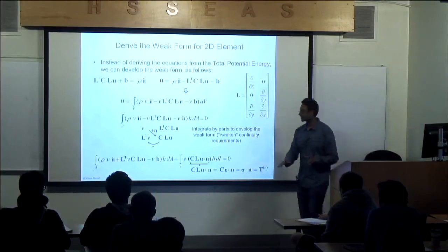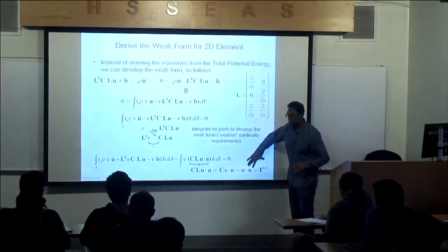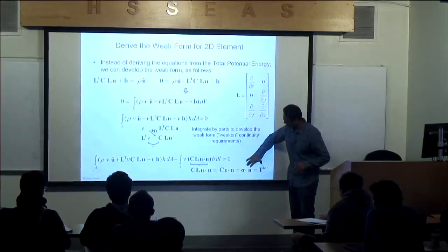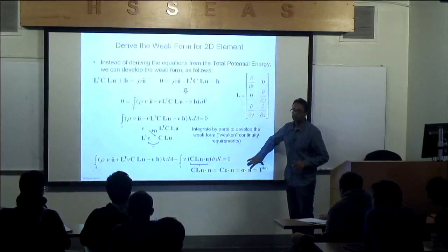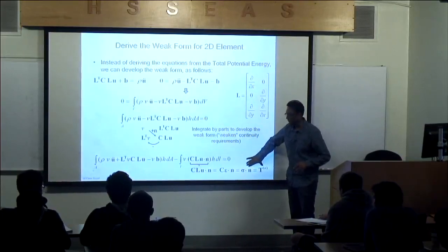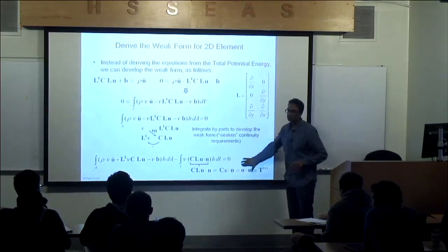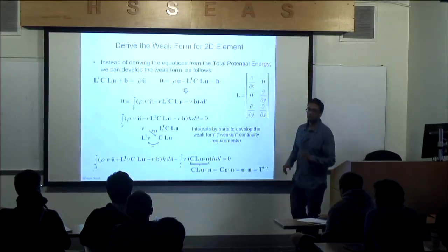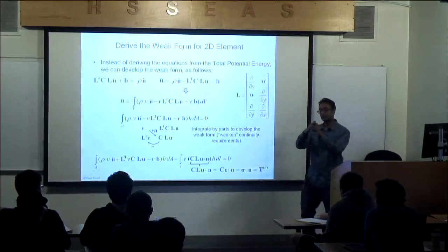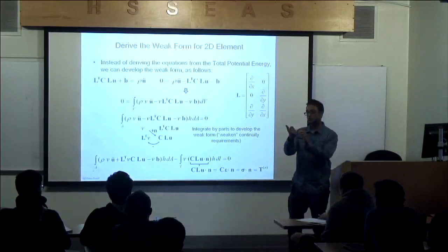If you take a more advanced course, I can show you by first principle that this is actually an equation that is true. And I covered that maybe lecture number 4. But in a more advanced course, this is called Cauchy's relationship. Okay? Knowing the stresses inside the boundary, knowing the normal, you know how that traction relates to the stresses at the boundary.